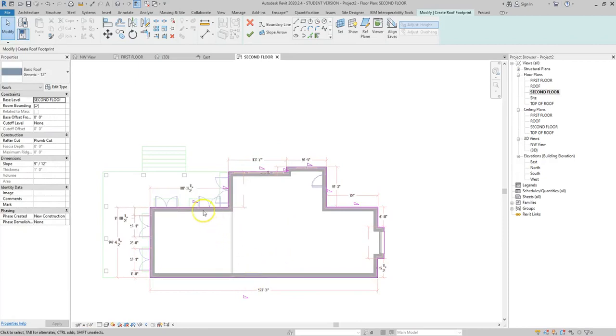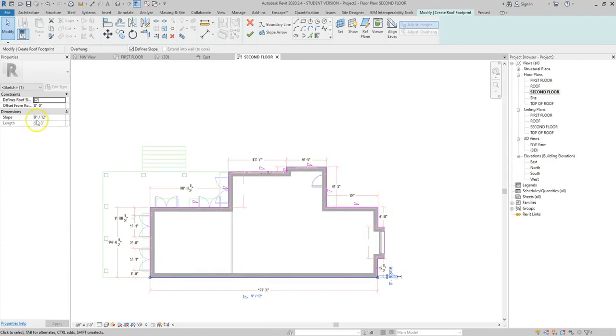So now I have this side and this side that define the roof slope. When I click on that line, the roof slope is 9 inches over 12 foot. So that's rise over run. That's a relatively steep roof, but that's something we can look at if we don't know the actual dimension, and we can adjust it later.